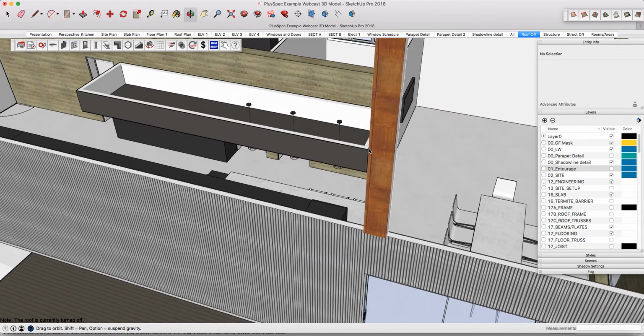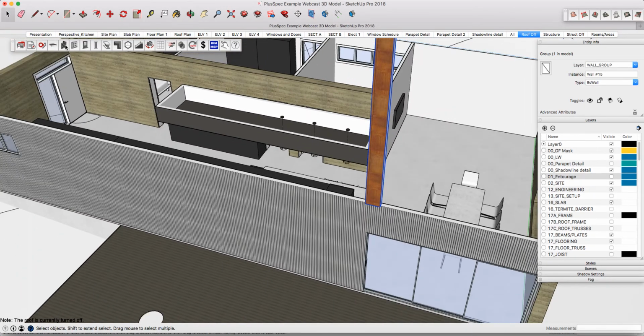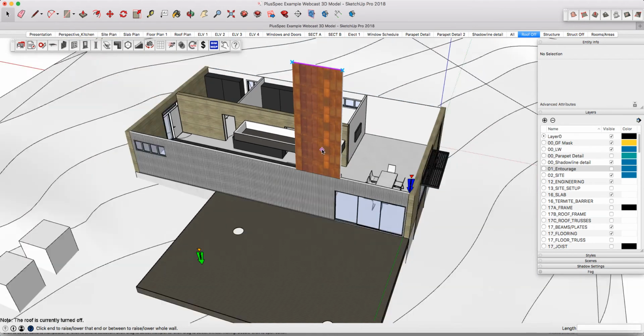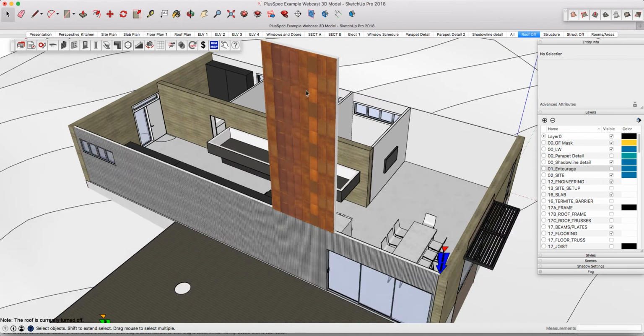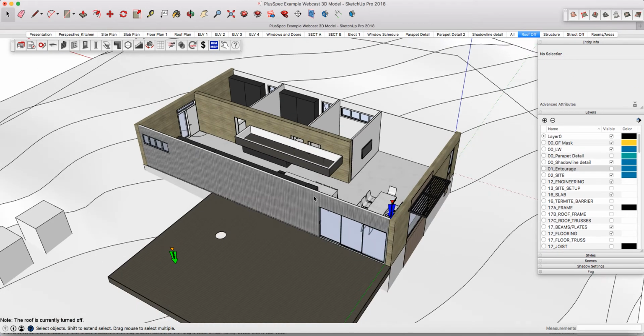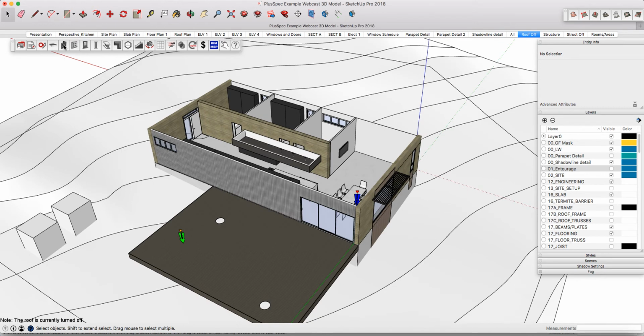I can draw with that material. And obviously, because the wall tool is parametric, I'll just quickly extend it so you can see how it looks. These are smart materials, and when I click on my takeoff, this new custom material will be calculated. Most of you should know that. And you can do that for everything.